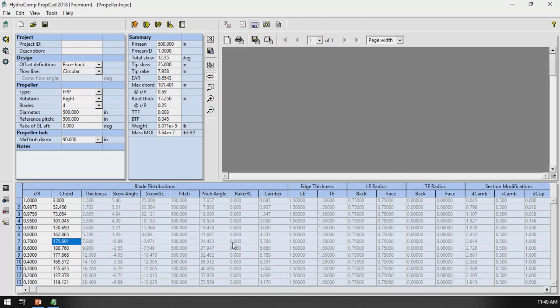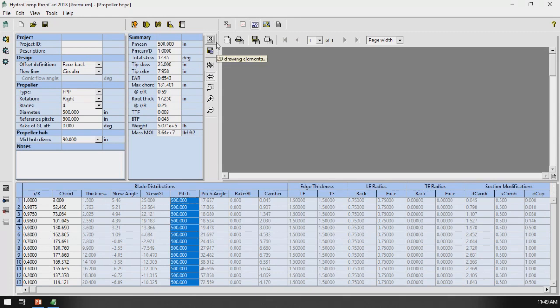So if you import 1, 2, 3 scans and they're all slightly different, they should in theory have slightly different parameters that get derived. And so you could go to the reports or the drawing in order to see those parameters. And you could compare, okay, the pitch of the 70 here is 28, but in this other scan, it's 29. And that way you have an objective way to compare those scans.